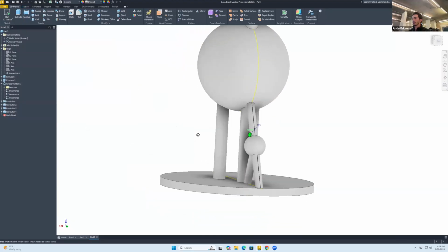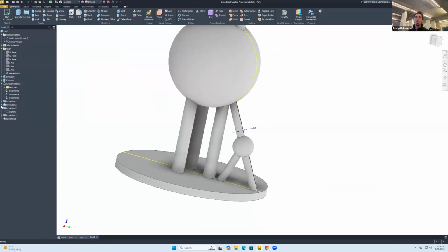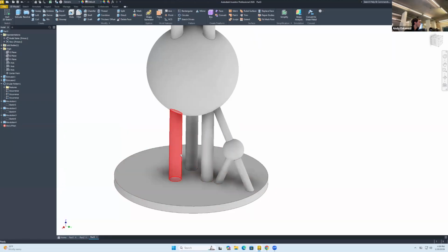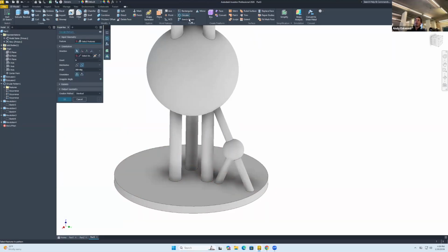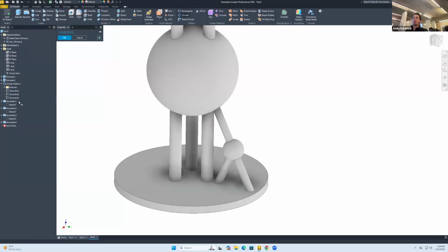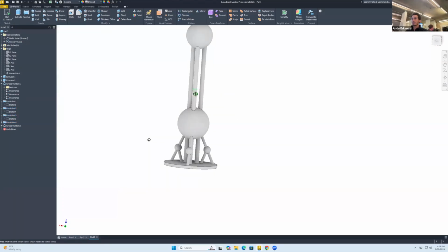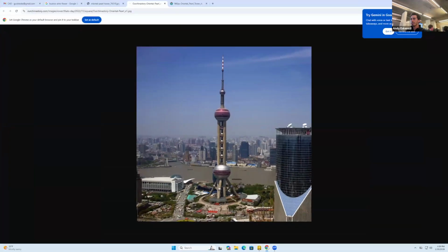Okay. So you got that ball in there. And let me go to all the previous ones in here, and let me hide them. There we go. So what do we do from here? A circular pattern. So circular, select features, 1, 2, 3. Select direction that, and I want 3. There we go. So that is roughly the base of that stuff, and then you can color it.